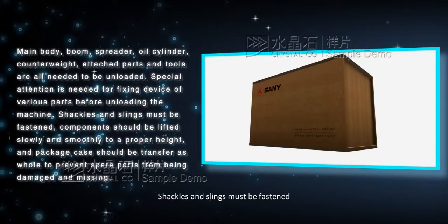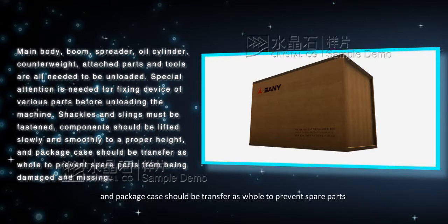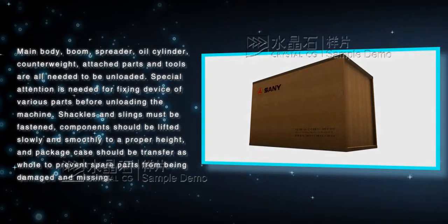Shackles and slings must be fastened. Components should be lifted slowly and smoothly to a proper height, and package case should be transferred as whole to prevent spare parts from being damaged and missing.